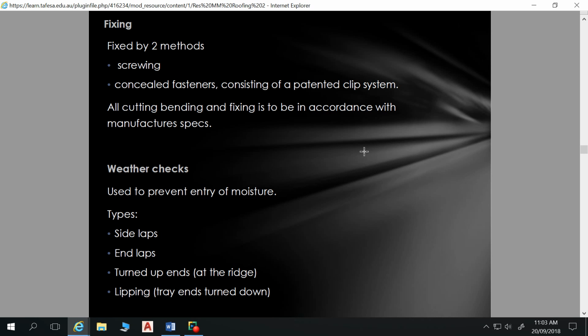And you see the oxidisation when they've done that, like pulled a few roofs. I've seen it where somebody laid sheets over a long skillion roof, laid the top ones first, and then the bottom ones. Can anybody think of what the issue with that is? Besides Doug. Wouldn't the air get trapped in them instead of having it this way? Yeah, exactly. So the water's going to run down here, and then it's going to run straight under that sheet.